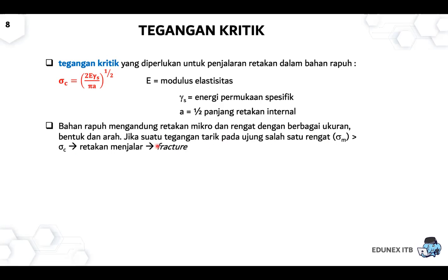If you have a tensile load at one of the flaws that is higher than the critical stress, your crack will propagate and there is a fracture. So we have to ensure that our tensile stress is not higher than the critical stress.